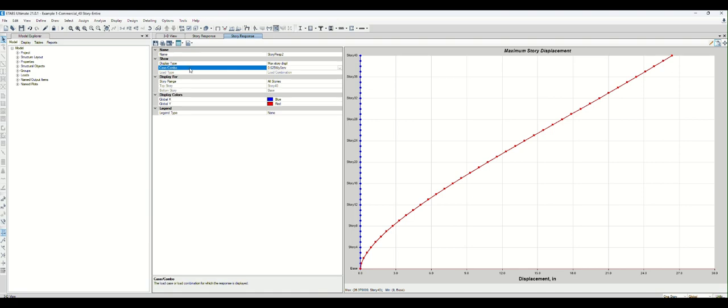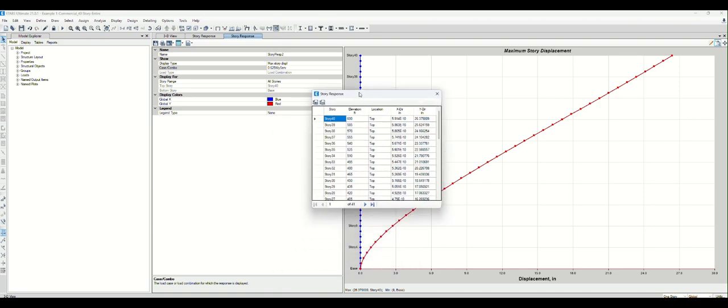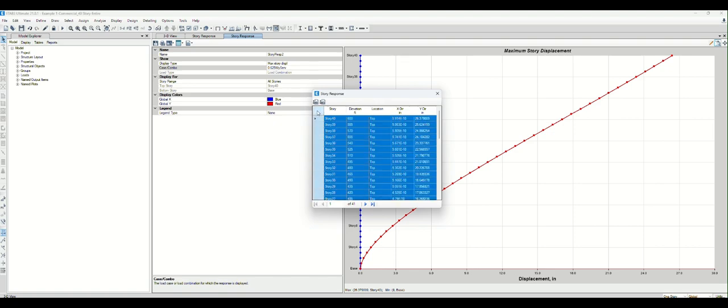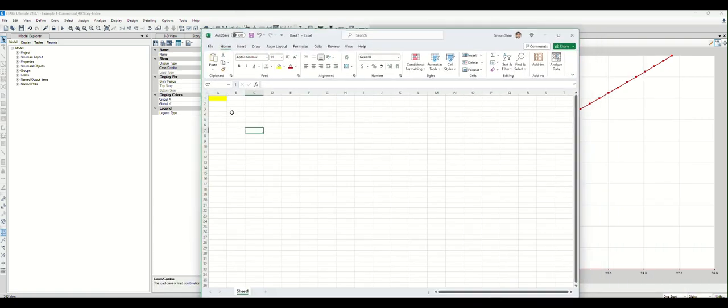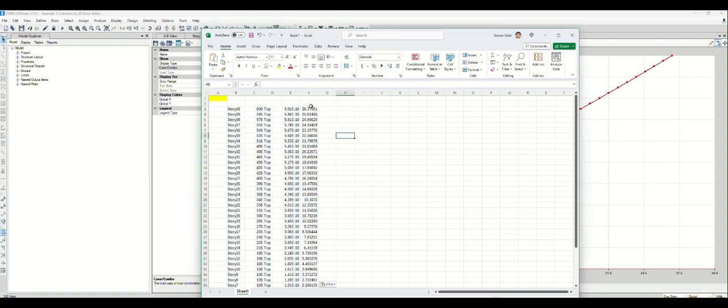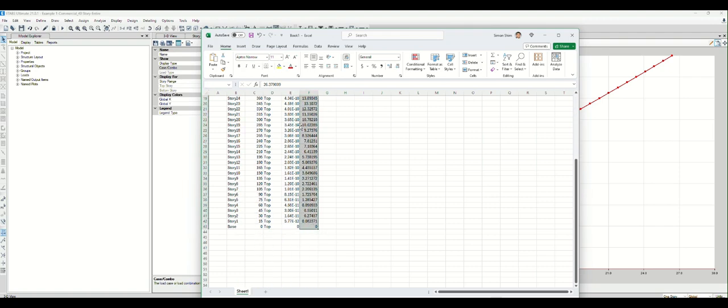So you can see that there are many ways you could pull out the data. I'm gonna pull it out. Click this Excel, format it. So you see all the deflections in the Y direction. I'm gonna select and copy, and I'm gonna put it here. So this is, let's say, deflection in Y, right? In inches. So we're gonna just continuously increase our stiffness,